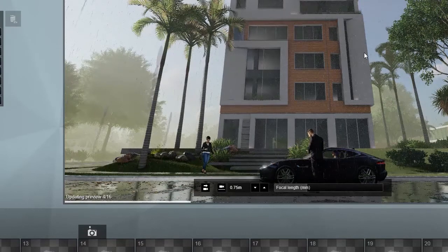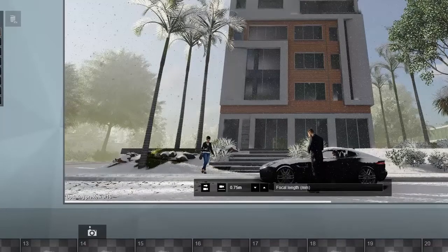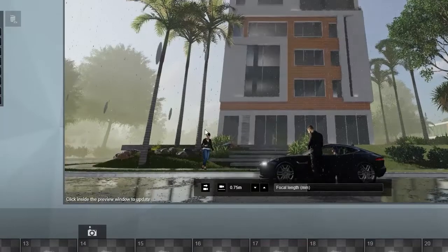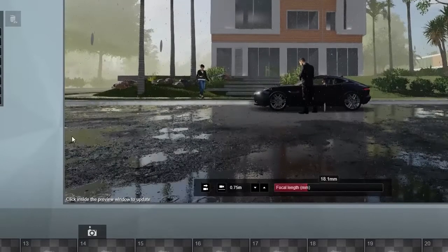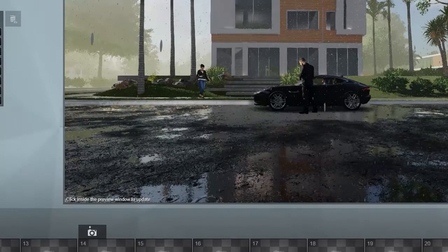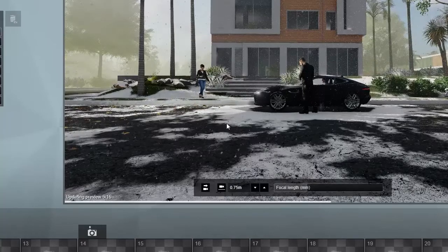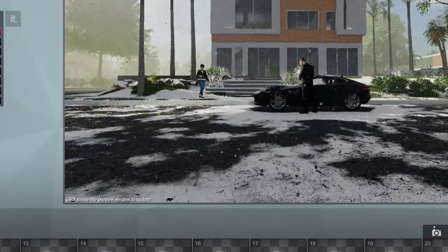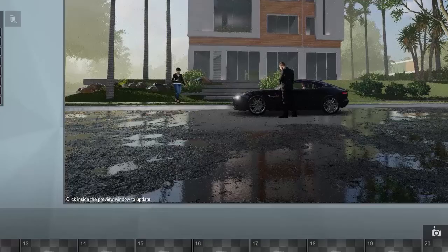And from precipitation we can add snow, we can add rain. At the same time, with a very simple change, we can change it to rain or to snow. And in phase, you can see the water on your asphalt. It's the same story for snow as well. That's how much snow you have on the ground. We select rain, and we put this phase on this.